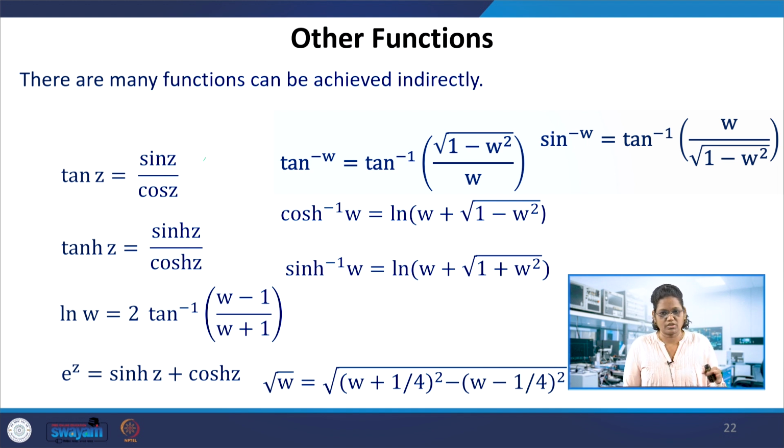So the three generalized equations of the CORDIC algorithm can be made into a module. You write a Verilog code in which the three equations can be stated for different iterations, and the module can follow the iterations depending on whether it is set to rotation mode or vectoring mode. That should be one module which can at least work for the rotation mode and vectoring mode of the circular coordinates separately, so that we can get cos and sin theta, or the x and y values required in the circular coordinate rotation and vectoring mode.